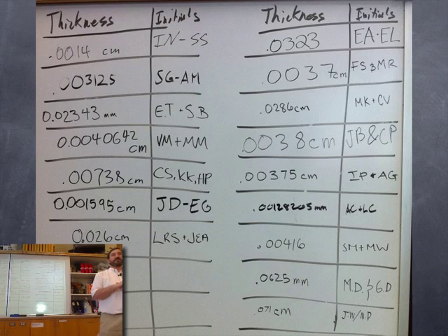The numbers that we use are measured values. We used a piece of equipment to measure them. If you used one of the rulers that was only marked in centimeters, and I put some of them out there, you may have seen some of them that only had centimeter marks and no little tiny millimeter marks, you're going to get a different one than if you used one that was marked in the millimeters.